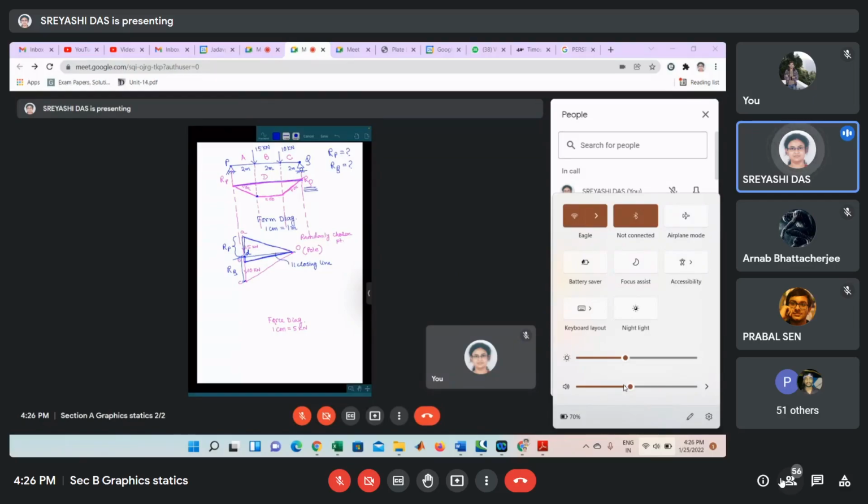Because you see, this is OA, this is OB. We have drawn these two lines parallel. And if this is a 15 kilonewton load here, then at this joint it must be in equilibrium, like this. So a triangle here, small a, small b, O, denotes the equilibrium of forces at a particular joint.